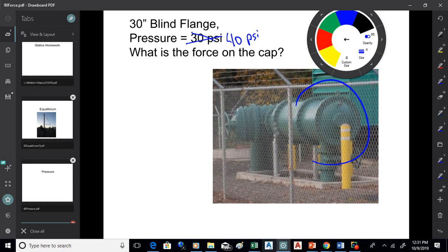I heard a story once from a guy that worked down in Eugene. They had a main going down a hill, so they were building up extra pressure because they're on a big hill, and they hadn't buried it completely. They kind of left it in the trench and just put the bedding around it, and they pressurized it. That thing just jumped up like a snake, and you got this big 8-inch water main just popping up out of the ground. Just be aware, okay? There's just a lot of force that builds up.